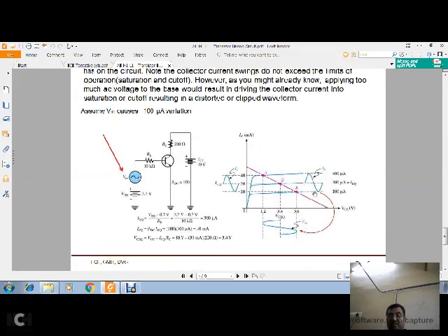So if it is the case, I am going to get this output curve, right? The middle one. When I draw my DC load line by applying KVL, somewhere here it intersects, and this becomes my Q point.